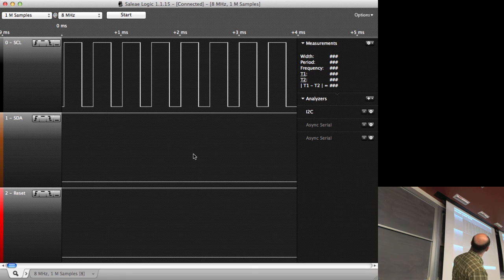Okay, something came out on channel 0. What type of signal do you think this is? Can we tell from this what it is? Yeah? A PWM signal? Could be. Goes up and down a little bit. Yes? Plus the logic analyzer measures only the high and low state. Okay, it does measure only high and low state. I'm mostly interested in the frequency, actually, right now of this signal. So it could be a PWM or it could be a frequency.